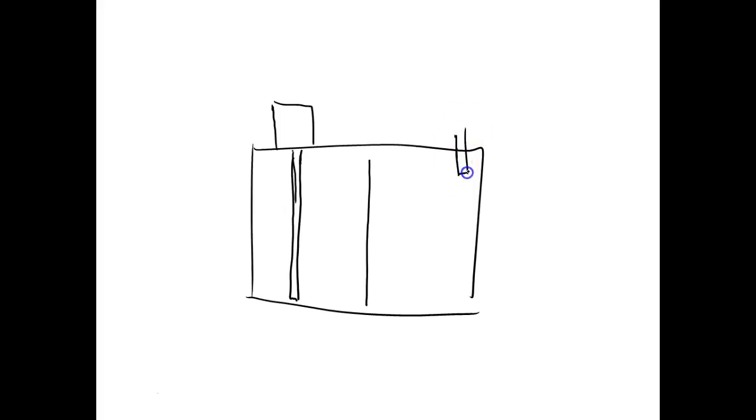Now sometimes they do this differently. Normally they'll come over here and drop this through a filter. And then, of course, it's going to fill up in here and then it'll drain in. Of course, it creates bubbles. And so that's why over here we have a baffle, right? So the bubbles can't get from this side over to this side. And it draws a level. So this is a typical tank.